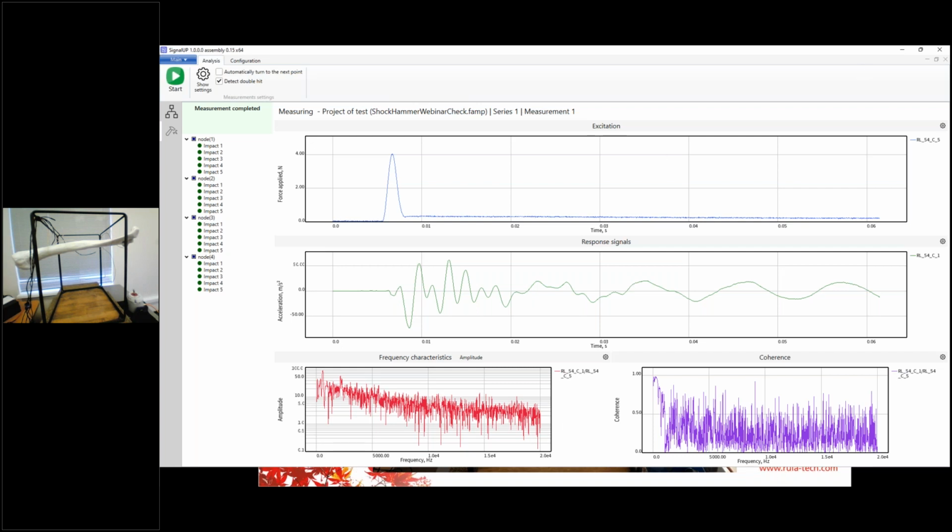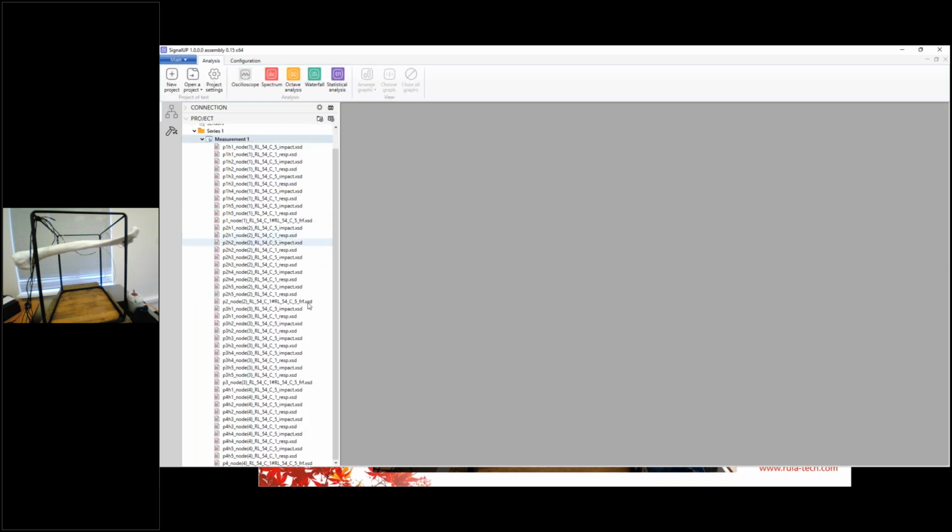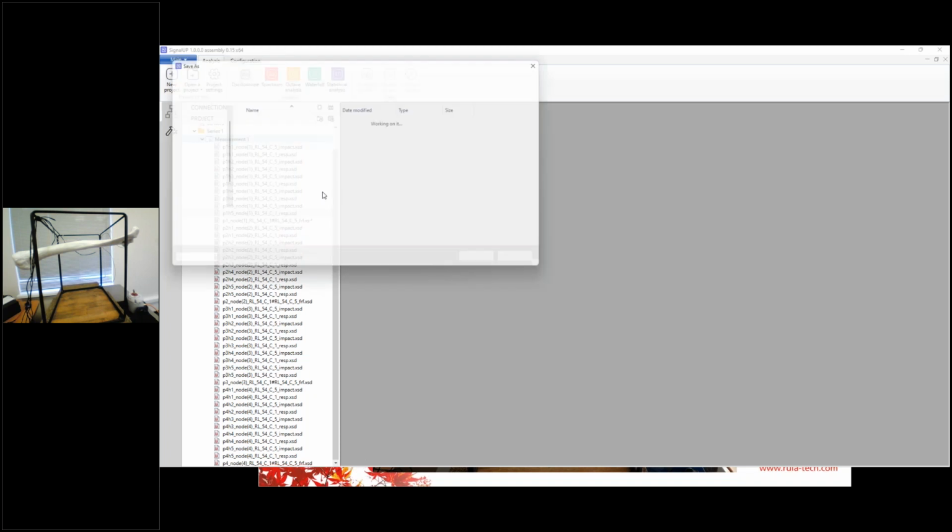And now we are ready to perform an analysis in modal analysis mode. Here you see the recordings of all our shocks, and we need to press make modal analysis project.